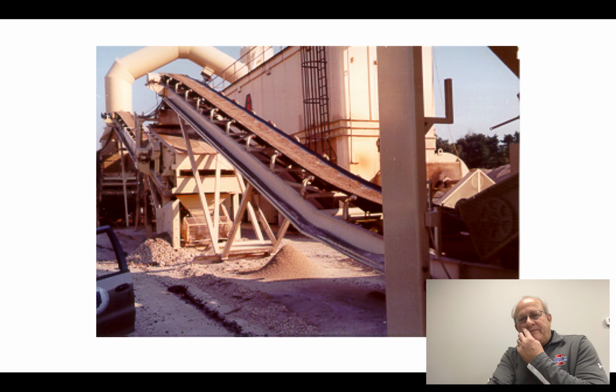This is the gathering conveyor coming out from underneath all the cold feed bins, going up to what they call a screen deck. In this case, you're really not sorting material. That screen deck up there is just to keep any large particles, oversized particles, or things like that out of your mix. It's amazing sometimes what'll come off these screen decks. We've had dead raccoons, we've had deer, you name it. Mostly comes out of places where there's natural sand, where they get into the piles and get buried.